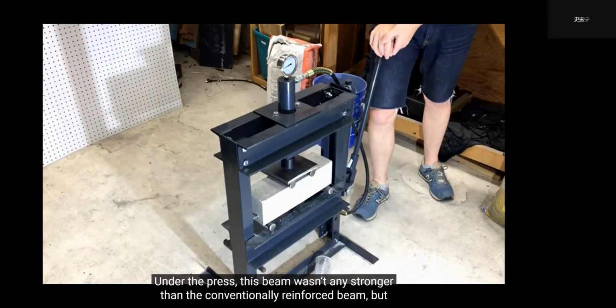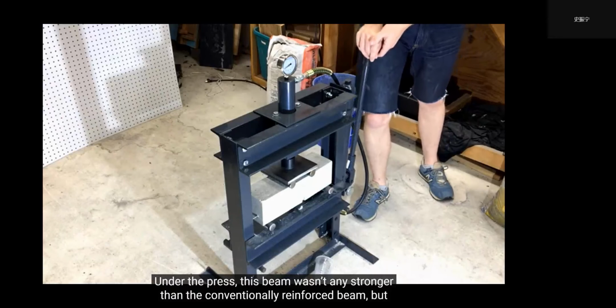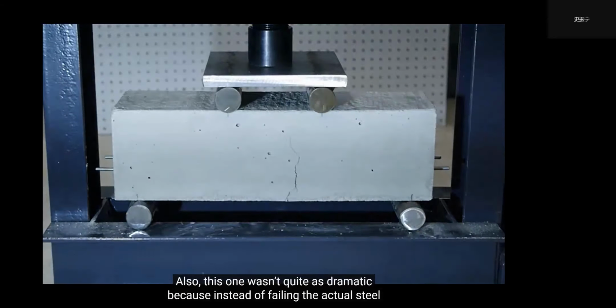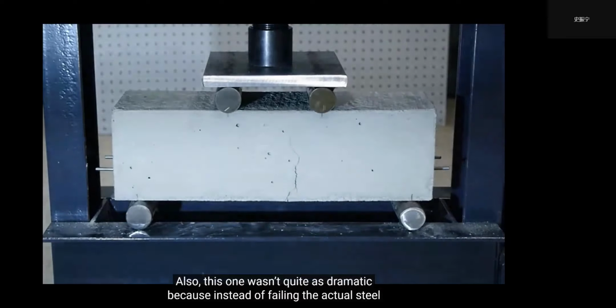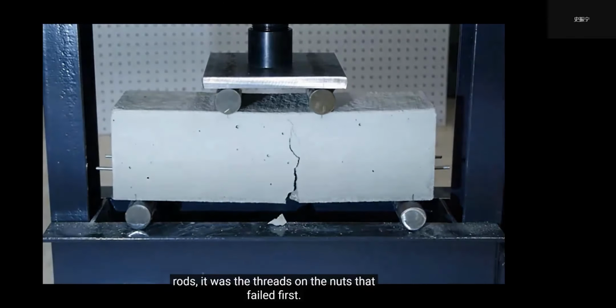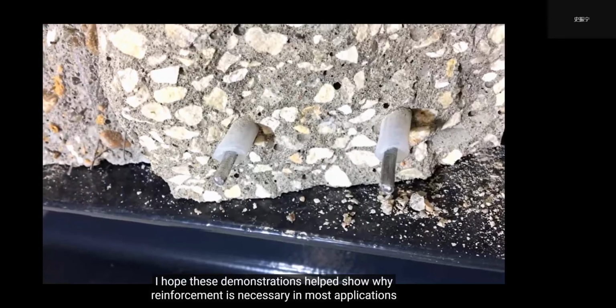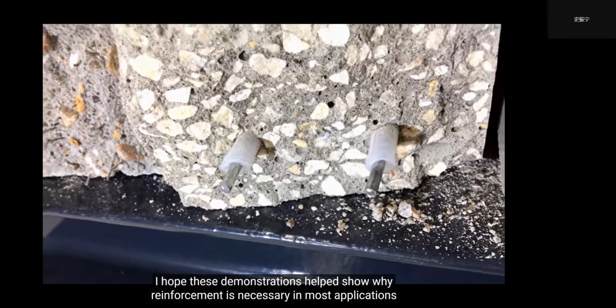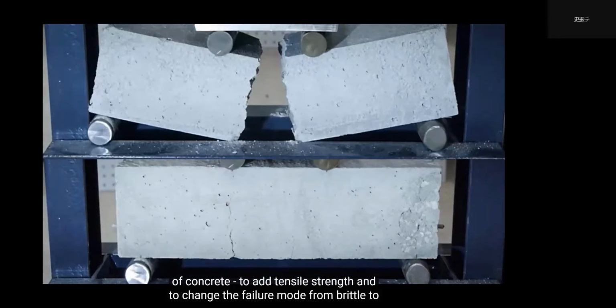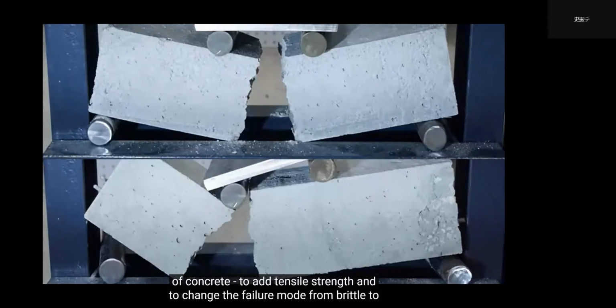Under the press, this beam wasn't any stronger than the conventionally reinforced beam, but it did take more pressure before the cracks formed. Also, this one wasn't quite as dramatic because instead of failing the actual steel rods, it was the threads on the nuts that failed first. I hope these demonstrations help show why reinforcement is necessary in most applications of concrete, to add tensile strength and to change the failure mode from brittle to ductile.